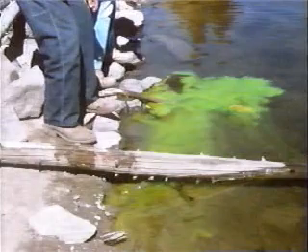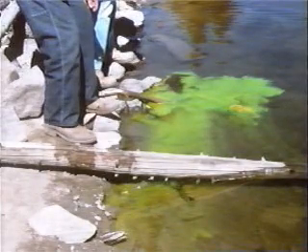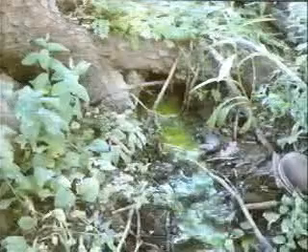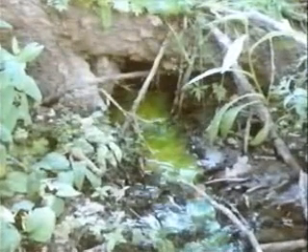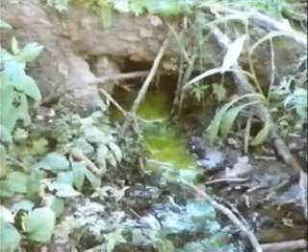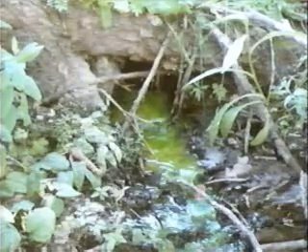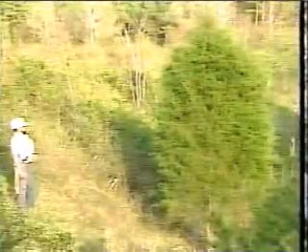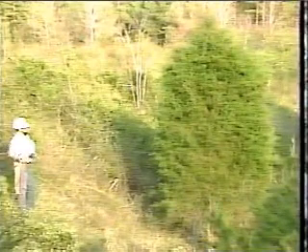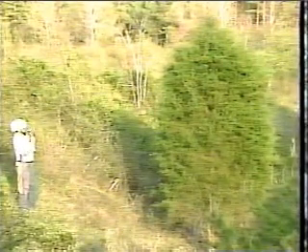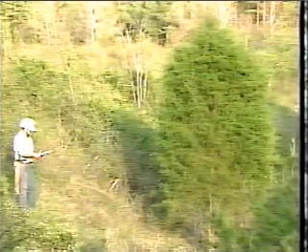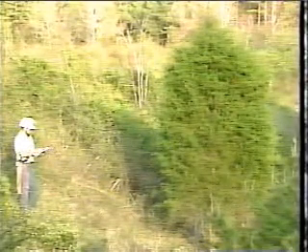As this seepage dye test shows, root systems of trees and shrubs penetrate into the dam's cross-section. When the vegetation dies, the decaying root system can provide paths for seepage leading to piping. Remember, trees and shrubs more than 2 feet high are undesirable when they're on or near embankment dams. There is agreement among dam safety engineers that when these trees and shrubs are small, they should be cut down.